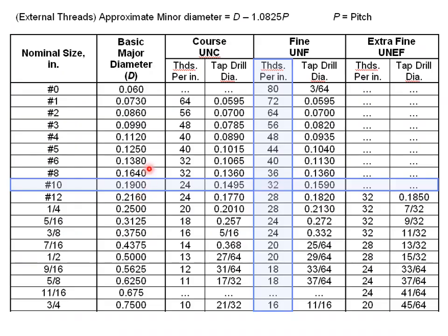Okay, in the back of your book, in the index area, there's this table. And this table is for threads involving inches. I don't have the entire table here. There's some rows missing with larger diameters. So let's take a look at ½ inch. If your boss tells you to order ½ inch threads, they're referring to 1/2, which is equal to 0.50 inches, and that's your major diameter for the threads.